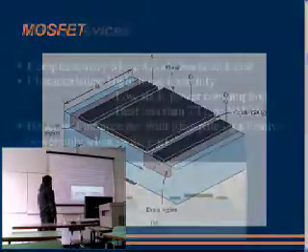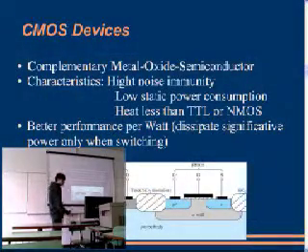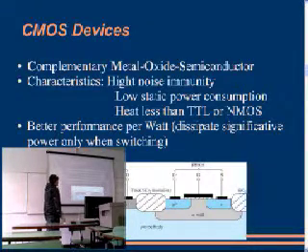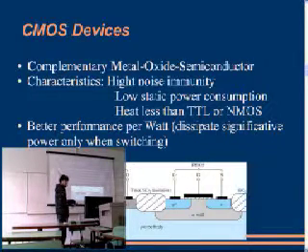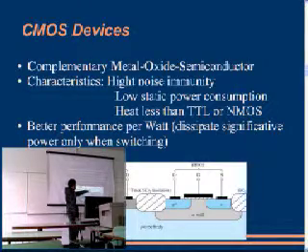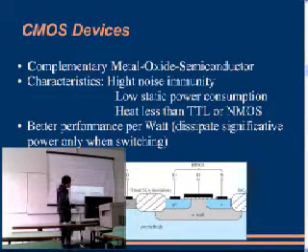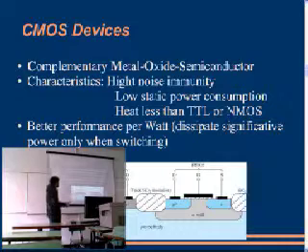So, the first improvement in the MOSFET transistor was the CMOS device. A CMOS device is basically two FET transistors in the same space, in the same die. We can control the gate of these transistors put together, and with one signal we can control the flow of current in both transistors, using just the signal on the gate. So why is this good for this kind of device?